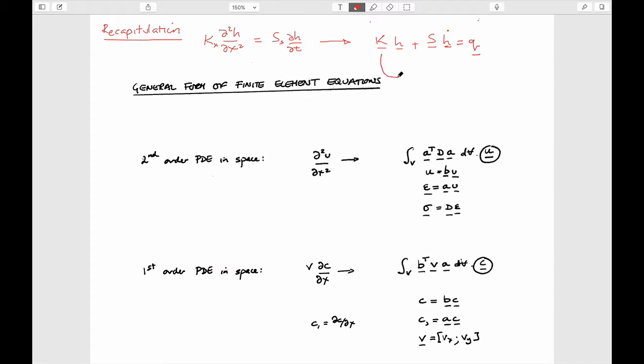And we saw that the K matrix was defined as something that looked like an integral: a term which related to the kinds of elements we had, a term which related to the constitutive equation which was of interest to us, in this case Darcy's law, and an integration.